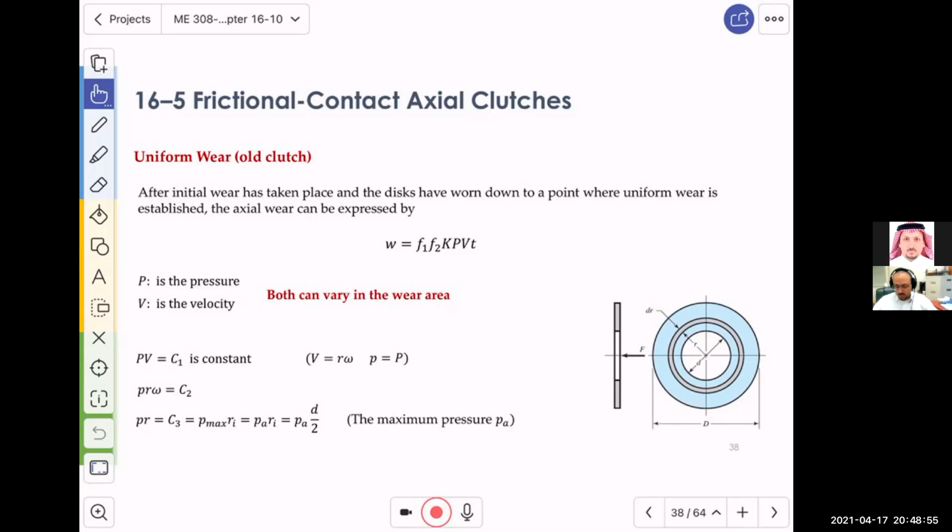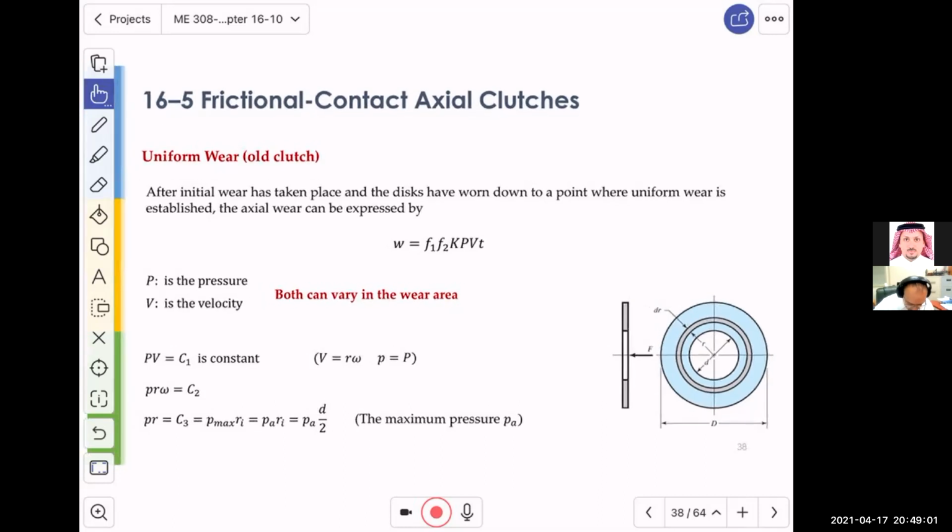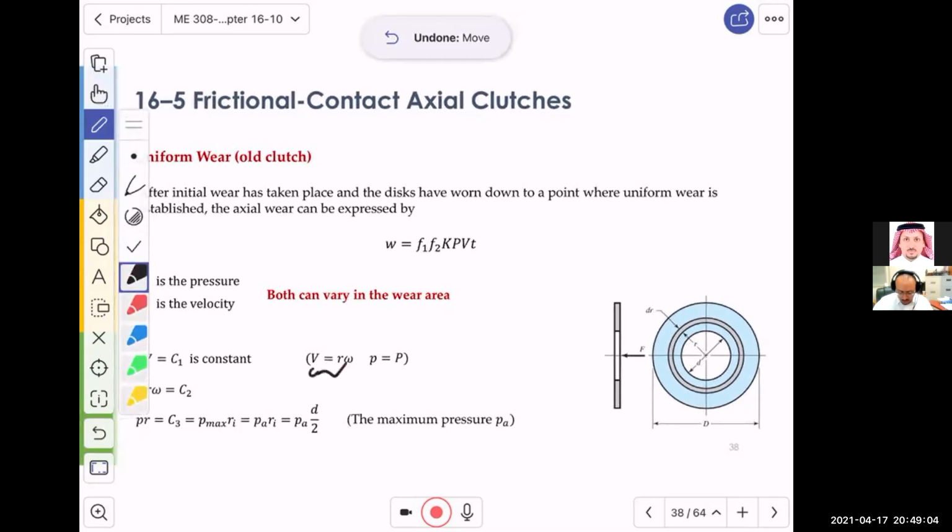If omega, which is the angular velocity of the disk, is constant, we know that V is equal to omega R. And since omega is constant, the only reason why V is different is because of R. So what are we going to do? We know that in our problem, as we said before, it's like an annulus, and we have a radius here. This radius R comes from d over 2, and we have a bigger radius over there, which comes from D capital over 2.